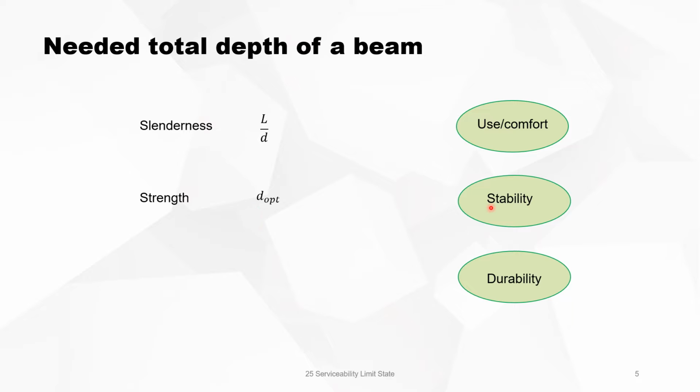In this criteria, you can also use the ductile depth, which is the depth where the behavior of the beam has a sufficient rotation capacity.